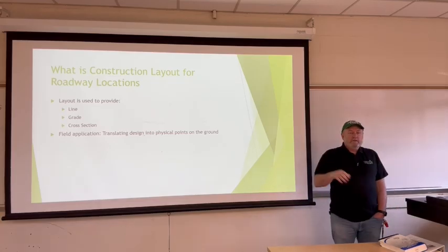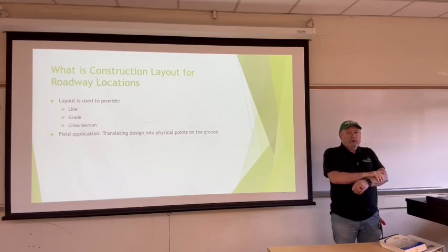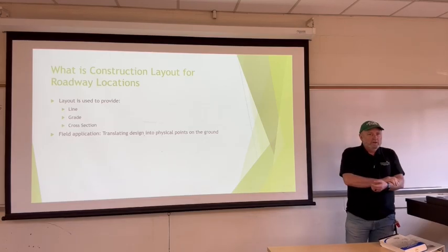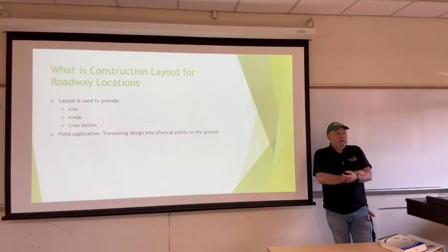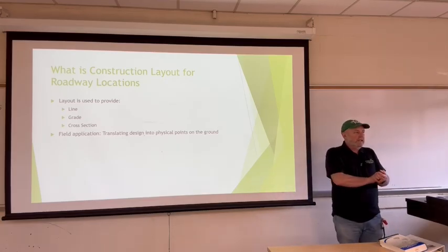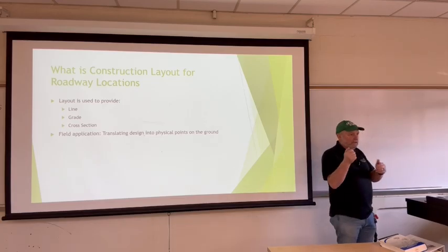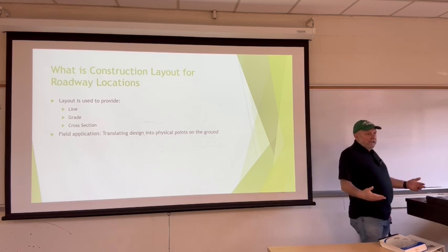We looked at profiles, and when we had to stake out roadways, looking at the profiles, all the curb elevations and vertical curve elevations were provided in the vertical curve itself. Or we had enough information in a data collector, the vertical profile put into the data collector, where we could just have it calculated for us.